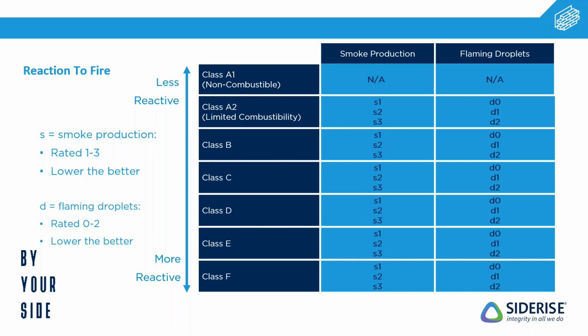With that ban in Regulation 7 on combustible materials, bear in mind that just because it has A1 and A2, it doesn't mean any A2 material. It specifically has S1 and D0. So you could have an A2 material that isn't S1 D0, it could be, say, S2 D0, and that wouldn't be suitable. So it's important to declare these little criteria that go along with different materials.